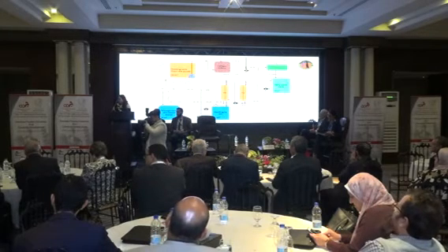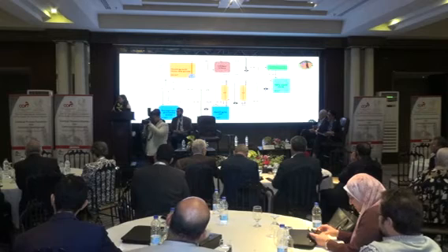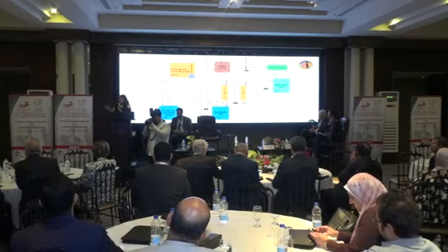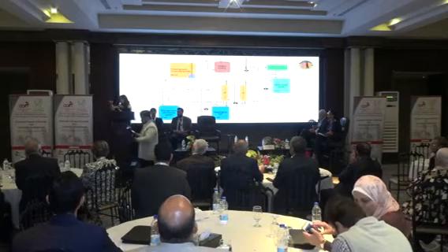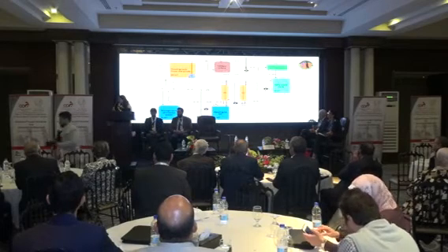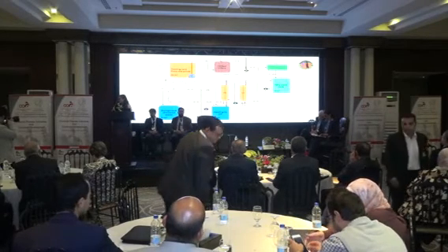I'm not sure about the specs for the steam regeneration, but if you lower the TDS from 130,000 to 5,000, you can do any further treatment with this water again. Maybe you can increase the units of the reverse osmosis, or as I said, the forward osmosis. As you increase these treatment units, you can lower the TDS so it can be used for steam generation.